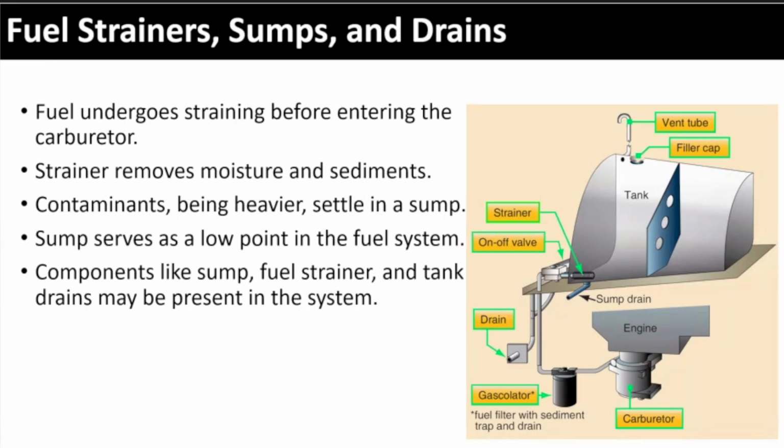We're calling it a gascolator, but it's another strainer down here. And there's a better picture of what that may look like in a couple of slides. But that strainer is another second line of defense to make sure you're catching sediment and water before it goes to that final step into the carburetor or the fuel injectors. Okay, so you see that low spot.